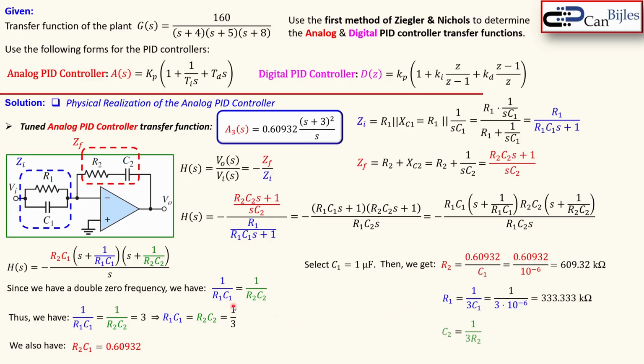Well, that is again using this expression where you see that C2 is 1 over 3 times R2. R2 is just calculated here. So substitute that and you will get here 547.06 nanofarads. So we have now all the 4 components by selecting one of the components here.